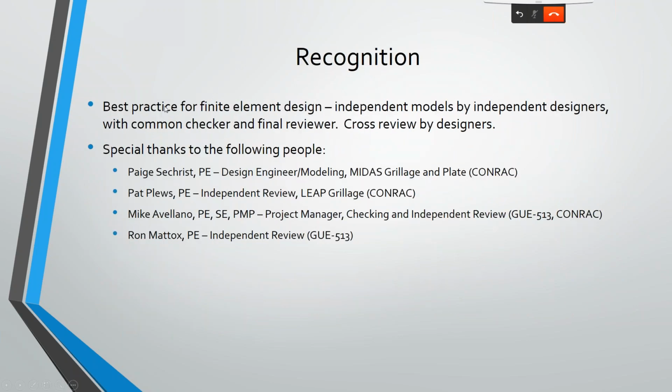And the best practice for the finite element, which is what we did here, is independent models by independent designers. So the LEAP model was done by a different person than the Midas models. And then they had a common checker and a common final reviewer. And there was cross-review by the two designers of each other's model. So having those two independent models converge, and they're done by different people, that's really important, and I think provides a very good cross-check that we're reasonable.